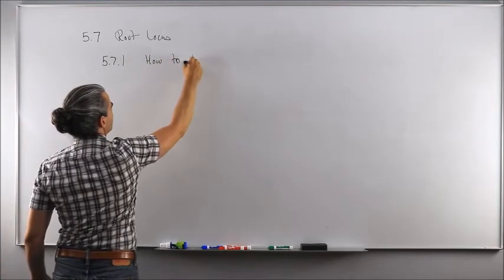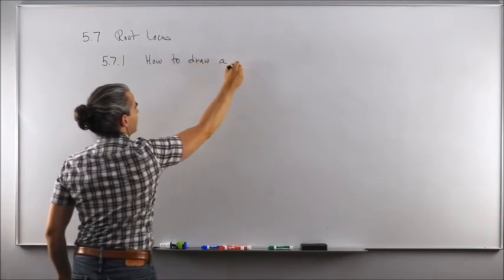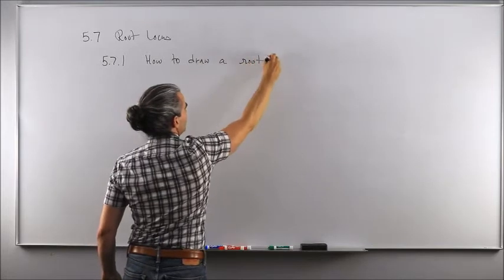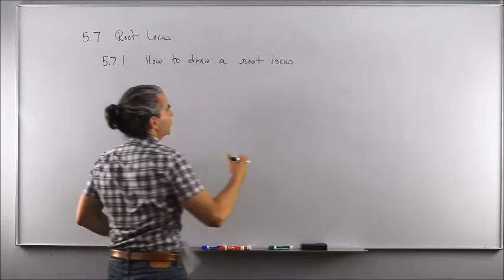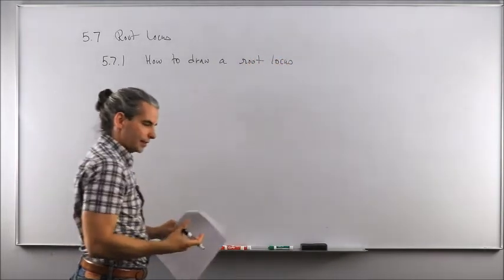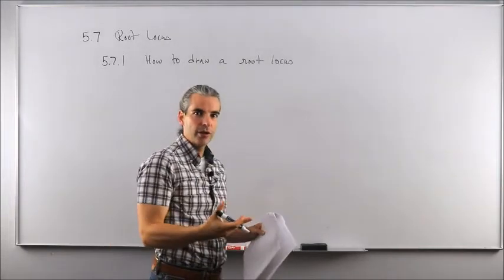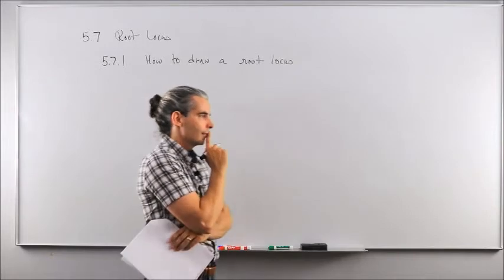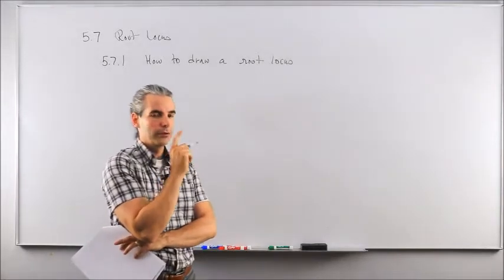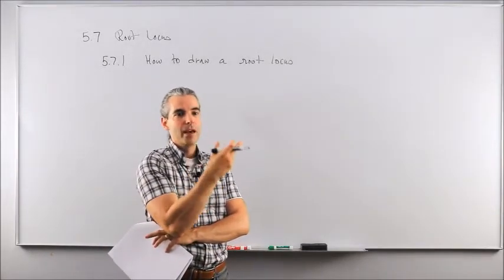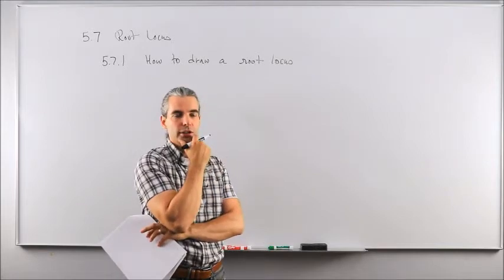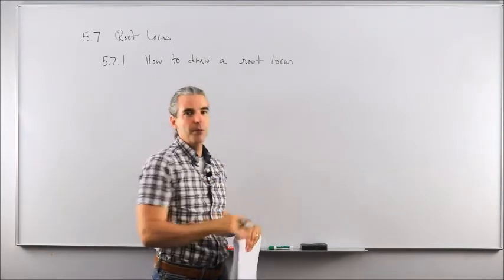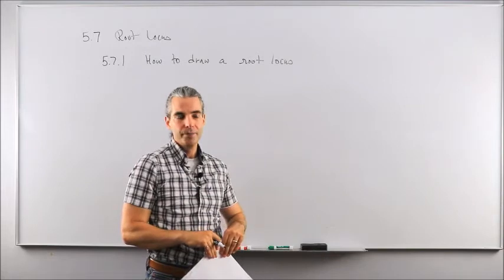how to draw a root locus that we can use as our basis in the next lecture as a design tool. Just by looking at the root locus, we'll say, gee, the root locus doesn't go through the desired pole locations. I better bend those branches and make sure that the poles end up exactly where I want them to be.